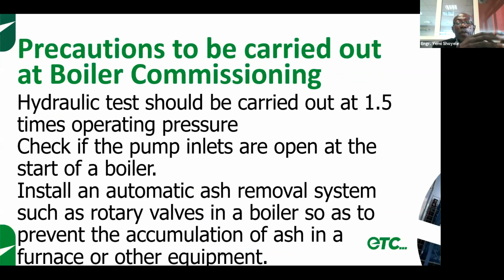Now there are precautions to be carried out at boiler commissioning. Hydraulic test needs to be carried out. Hydraulic test is subjecting the mud drum and steam drum, or any other pressure vessel, to hydraulic test, and this is done with 1.5 times the normal operating pressure. Okay. Now, at the start of the boiler, before you commission the boiler, you've got to check if the feed pump outlets are open. Always ensure that before you even start at all, the feed pump outlets are open.